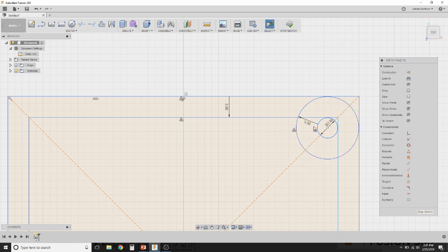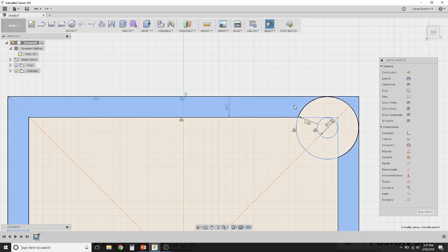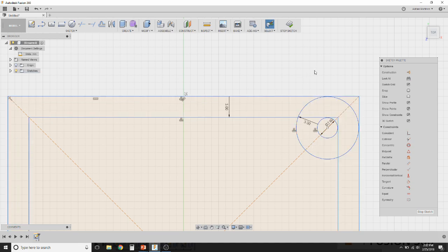All right. Now we've got some lines here. Pretty soon we're going to be lofting this, and if we do that, you're going to need to hold the shift key, click in the first place, click in the next place, click in another place in order to grab everything that you need, and that's a little bit time consuming. You don't want to have to do that every time, and if you're doing something very intricate, sometimes it's easy to miss a certain spot, and you'll end up with holes inside the middle of your object, and that's not really a good thing to do.